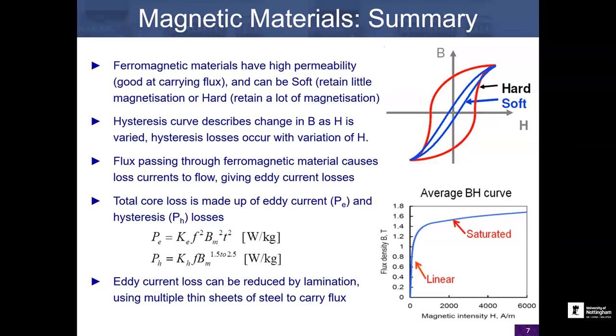We also defined a little bit the losses in these materials, how we have two sets of losses. We have a loss from eddy currents, currents circulating in the ferromagnetic material itself, and a loss from hysteresis, which is the loss behaviour of cycling these magnetic circuits. As we drive a flux change in them, we actually drive a physical change in the crystal domains, which manifests as heat and losses. And we can define these broad behaviours with a BH curve like this.